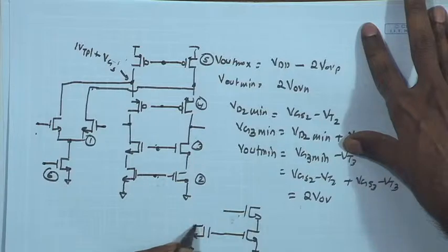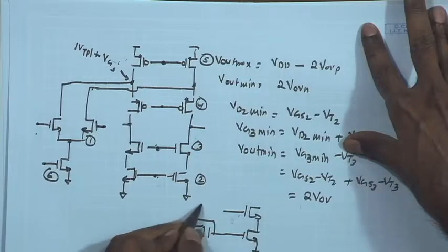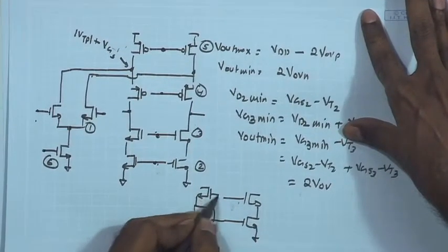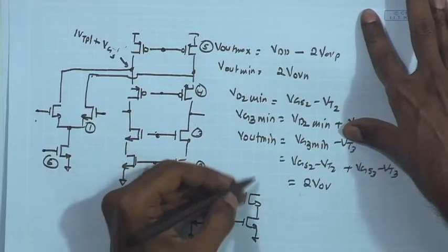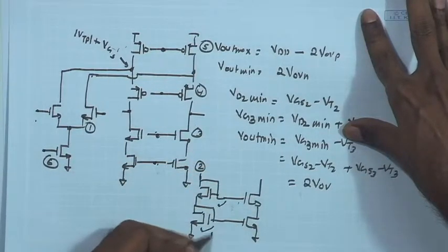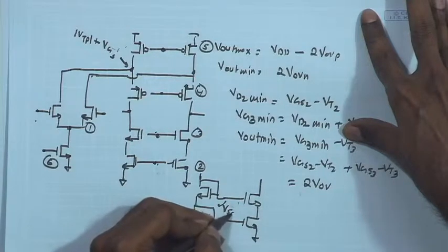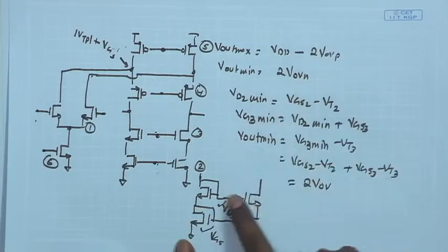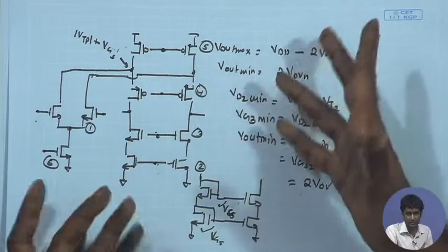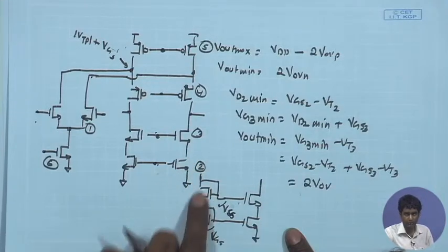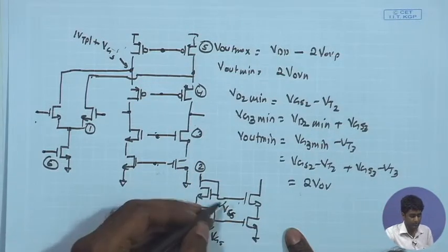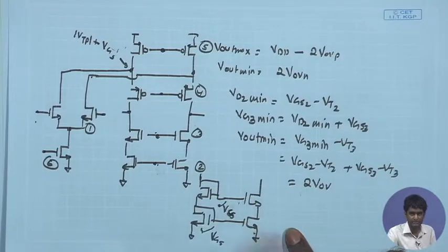Just like we do it for a simple current mirror, we can use a cascode mirror, and you can put a reference current in the cascode branch, and that is going to develop a VGS over here, another VGS over here, and that is going to provide the right VGS for these two MOSFETs. That is basically our simple cascode mirror, where on one side you have a stacked diode connected transistor, and that is giving you an appropriate value of VGS to bias these two transistors.